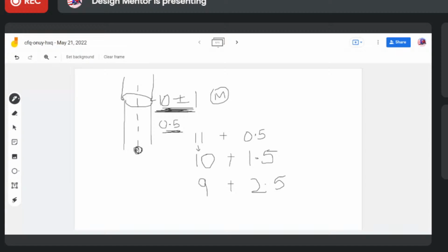So the manufacturer knows this much error here and there is okay. The part can get manufactured at 10.5 or 11 mm, it's fine. It won't be like, I want the part at 10 mm, otherwise I'll throw it in the dustbin. It's not like that. So this is flexibility for the manufacturer. We have a size tolerance for the part itself, and the positional tolerance is for where the part is getting placed and how much.